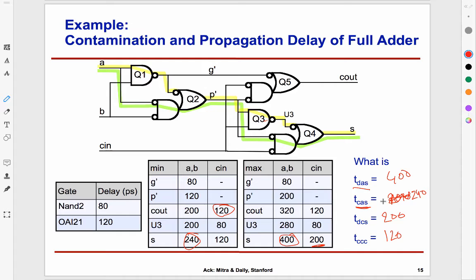What that means is that the inverted version of a function is faster than the positive version. So NAND is faster than AND. So actually, the reason we are seeing it is that if we were to have an AND and not have that bubble, it would actually be slower, because I'll have to put inverters there to make that happen.